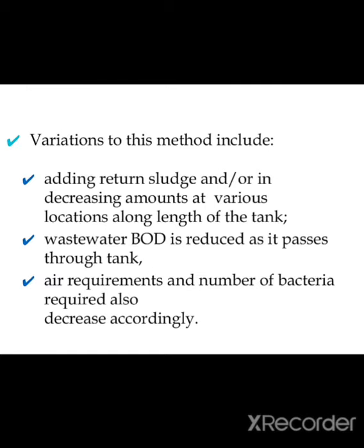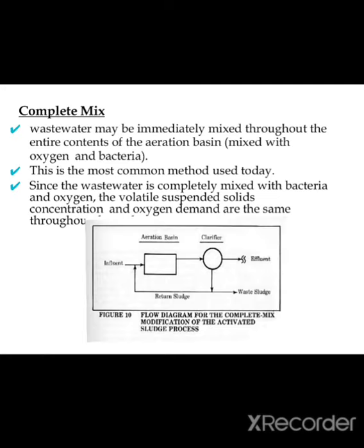Variation to this method, which includes adding return sludge in a decreasing amount at various locations along the length of the tank, wastewater BOD is reduced as it passes through the tank. Air requirement and number of bacteria required are also decreasing accordingly.